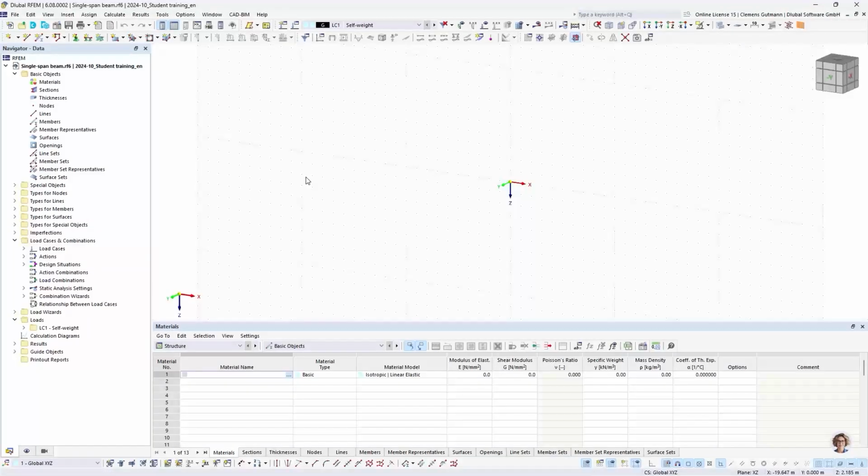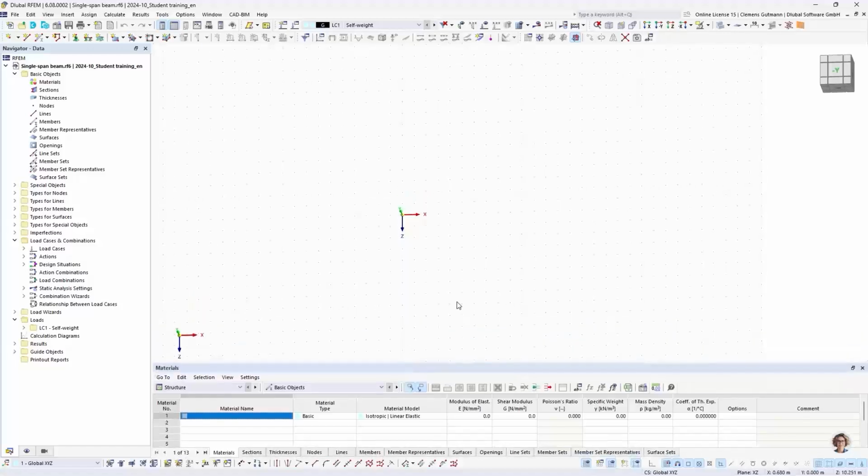And now everything brightens up and gets more colorful. We now see the image live that I showed you in the presentation before. So we have the main workspace in the middle, and it's a 3D workspace, as I told you before. To navigate this workspace, there are different possibilities. One is your mouse. If you click the mouse wheel and hold it, you can pan.